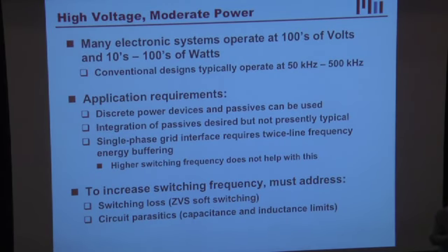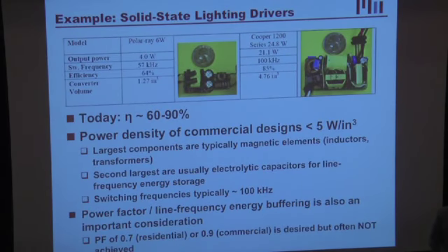So to give you a notion of this, in this case, we not only have to address loss, say the switching loss, we also have to address circuit parasitic limitations on turning up frequency, which I'll describe in more detail. But before I do that, perhaps I should give you some background of what this kind of application typically looks like today. And these are a couple of commercial designs that you'll find. We've taken apart many of these drivers just to see what the envelope of performance is.